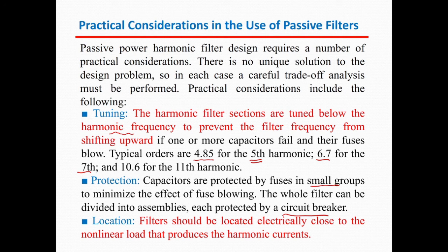The filter should be located electrically close to the non-linear load that produces the harmonic current. So if we would like to design a filter to get rid of the harmonic that is generated by a certain load, the filter should be located near that non-linear load that will generate